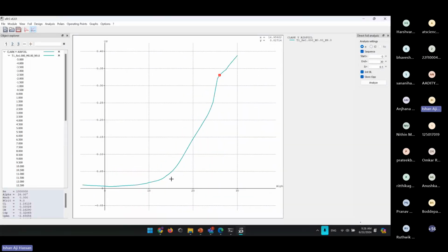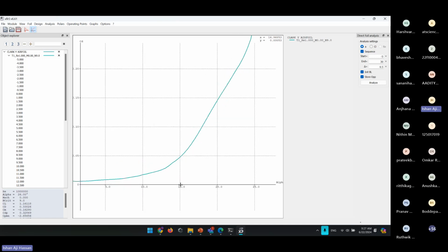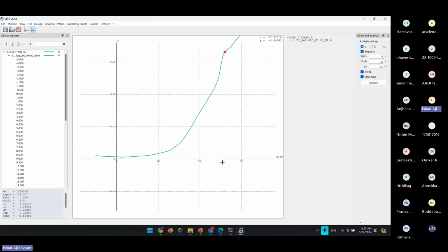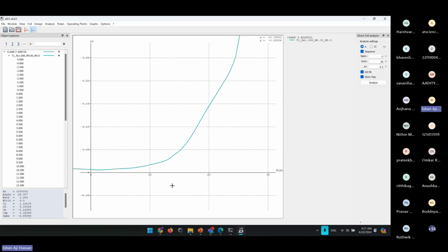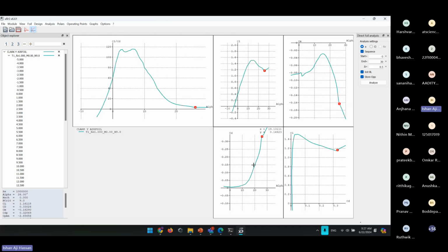Ideally, you want it to stall and increase the drag at a higher angle because you want to operate it at a higher angle of attack. But practically, airfoils typically have 15 degrees or less as a stall angle and as the drag increasing angle. So we should always try to stay below this angle. Yeah, so that is CL, CD.